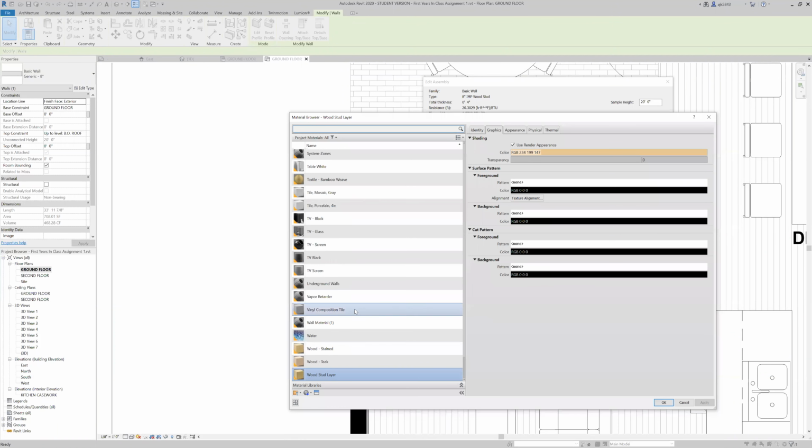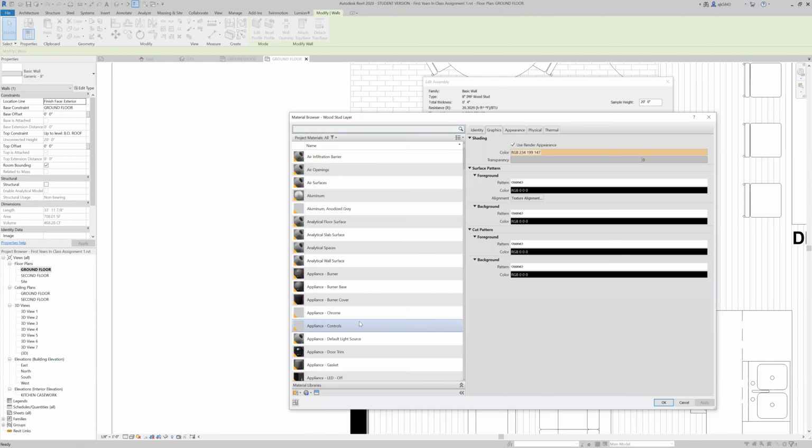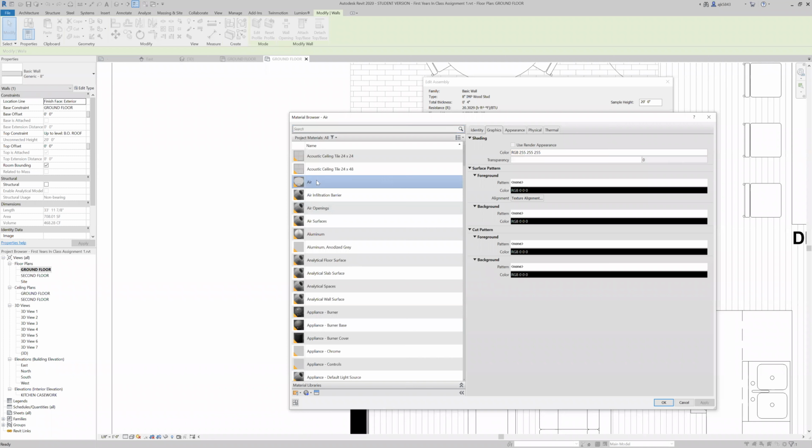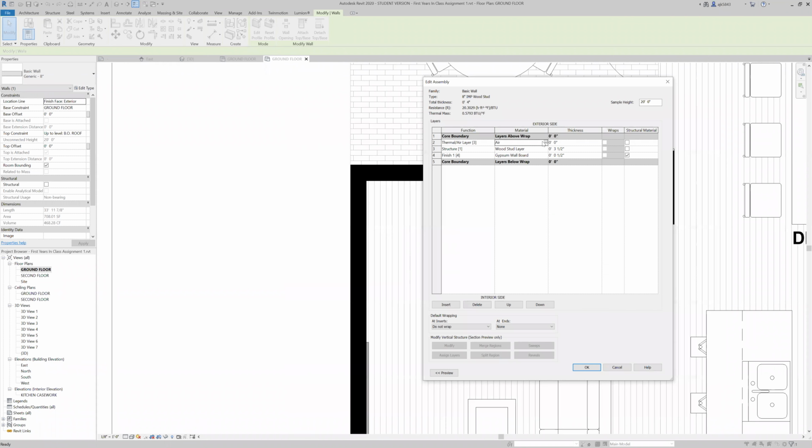So here, if we just do an air barrier, have just blank air material, so essentially nothing. And looks like right now our total thickness is 4 inches. So we could make that air barrier 2 inches, and then that would still allow for us to have some brackets that would then affix the metal panel to the house. So I'll go ahead and insert one more layer here.